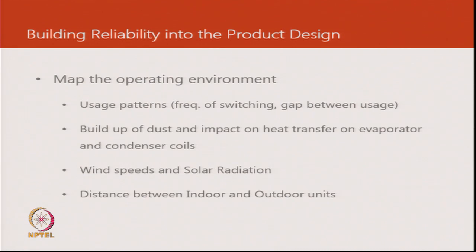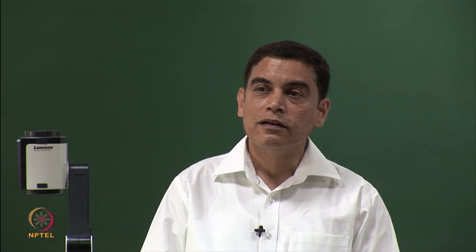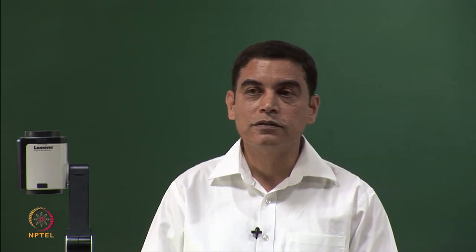Then one of you already identified this risk, buildup of dust and how it can impact. So probably you're talking about the condenser. The same thing happens in the evaporator, and it happens in the evaporator more because the evaporator is wet. So first the filters catch the dust, and then if we continue to delay cleaning the filter, some of the dust goes onto the coil and begins to create a thick crust, and then the heat transfer gets impacted. So we begin to see the unit operating at lower pressures, cooling is impacted, you might even have freeze up or frost conditions on the unit.